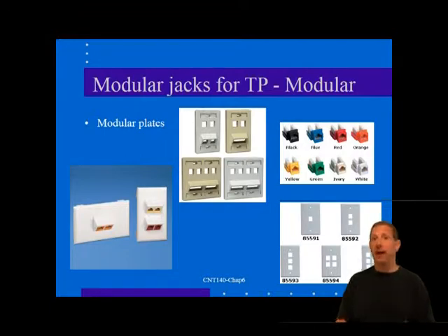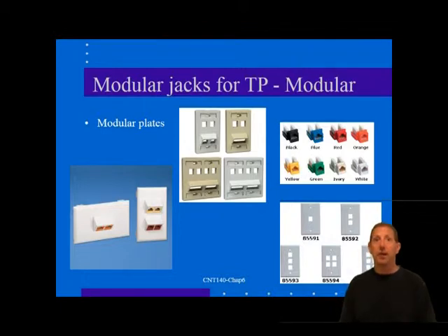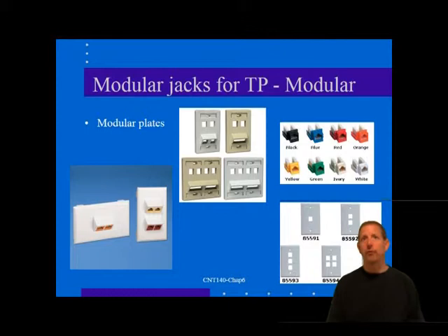The termination is accomplished by several types of IDC connectors, as we have described earlier and will be describing again later on. Now, the construction of the connector termination module generally produces much lower noise and crosstalk than with the conventional fixed jack plates. And for this reason, these jacks are preferred for LAN wiring, even in a Cat3 installation.